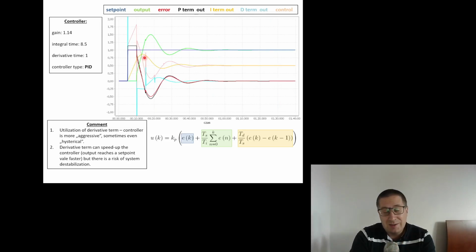So all the signals are related with some measurement noise. And if the controller reacts to those noises, it would be something really bad. Because, what are those noises? Suddenly the process output rises, then drops, then rises, drops. So this is the noise, right?